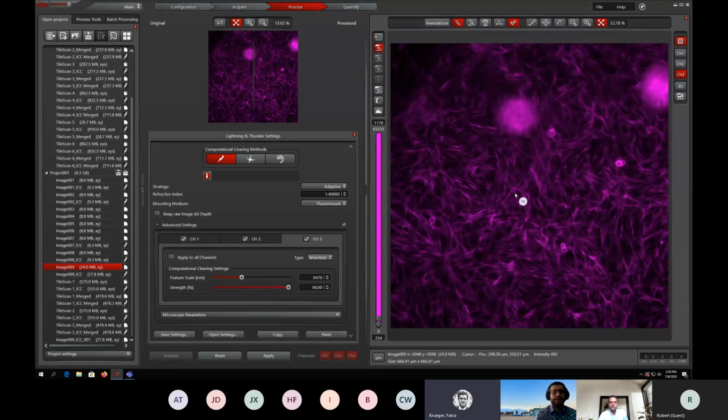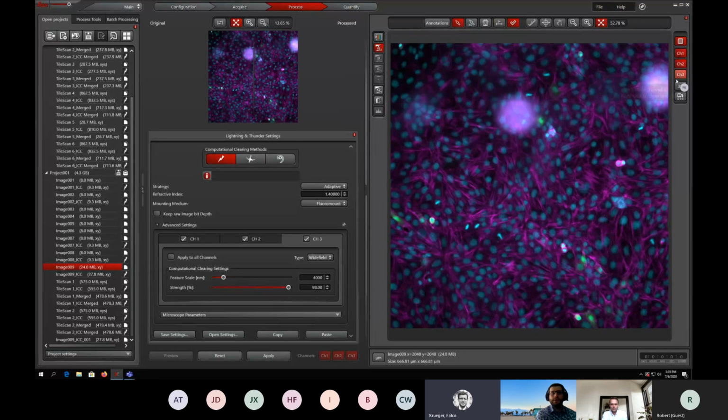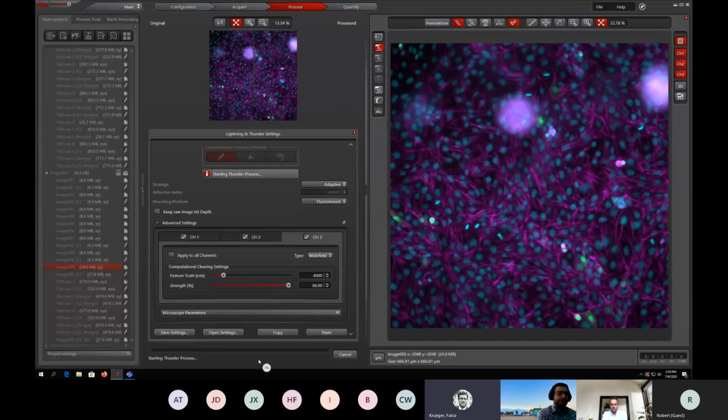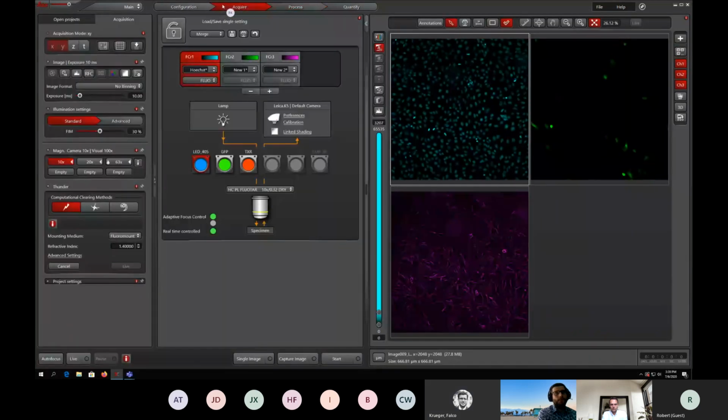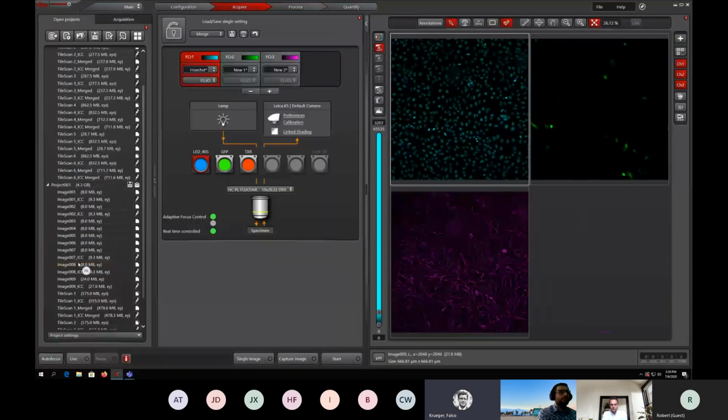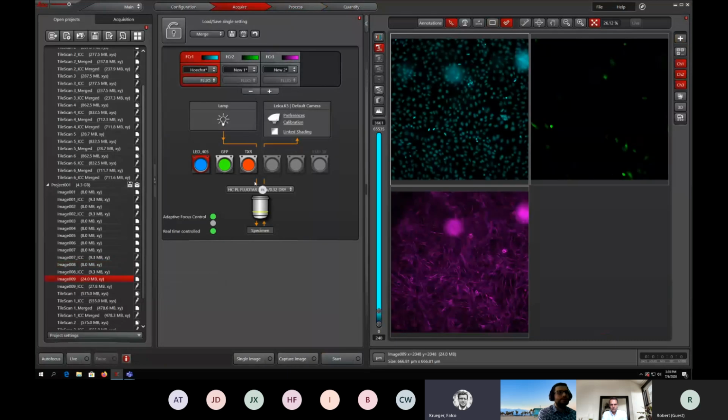That's why I would usually stay here with the default value. But for now, since we adjusted all the different settings, I will also go for a lower value, 4,000 microns. And we'll just see how the adjusted settings impact the image quality. So I will press apply now. All right. And now, as before, we will compare all the images.